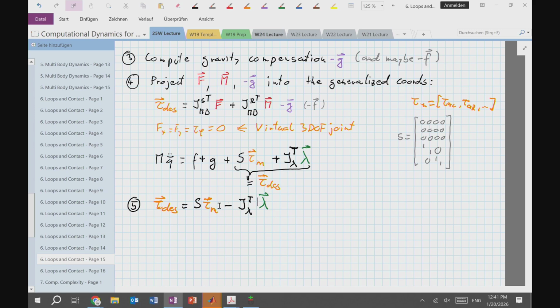I'm free falling. Yes? One question, but when the feet are not on the ground, they are 0, or in that case they don't exist? Same thing, right? This has dimension 0, so the Jacobian is an empty matrix. This doesn't exist. Mathematically, it doesn't make a difference. So that's free flight. There's nothing you can do, right? You will follow your ballistic trajectory no matter what.